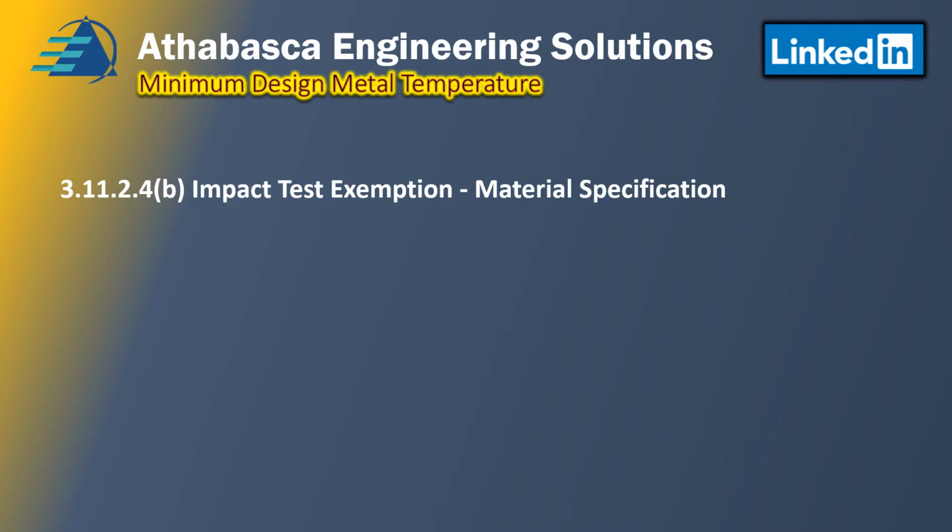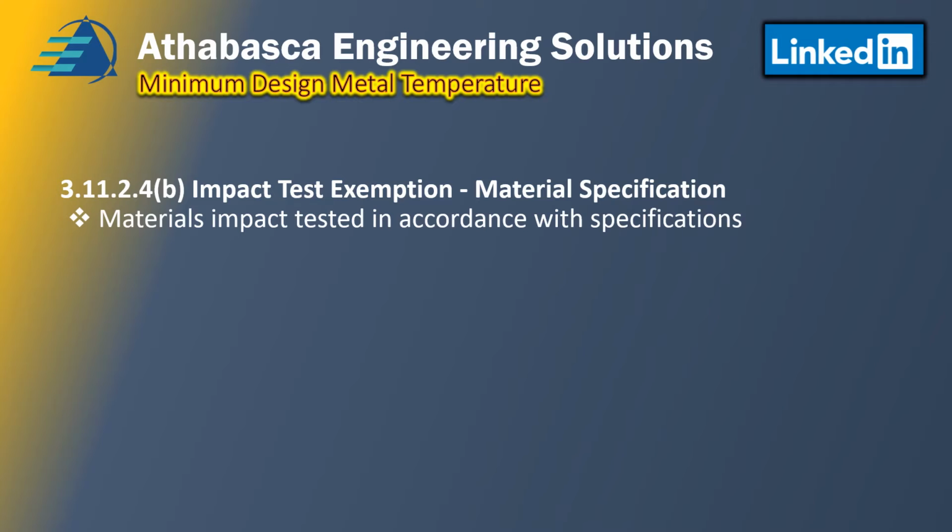3.11.2.4b: materials impact tested in accordance with specifications can receive an exemption, just like Division 1. Examples could be SA 333 or SA 350. You have to go to the subclasses to get the exact MDMTs.